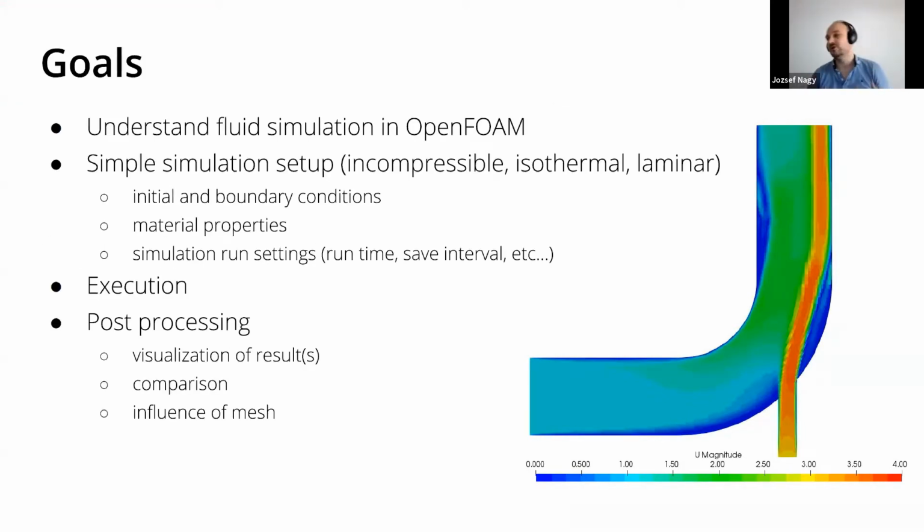So the goal of this simulation is to understand the fluid dynamic simulation in OpenFOAM and just the basic workflow. What do you do? Why do you do it? Because I remember when I started with OpenFOAM, I downloaded it, I went to the tutorials, and all I saw was a couple of folders and a couple of text files. And I thought to myself, okay, where do I click to open up this file? And yeah, you don't click, you modify text files, and then in a terminal, you run an application which reads in those text files and then runs the simulation accordingly and outputs your results. And then afterwards, you can visualize your results in a separate tool called ParaView.